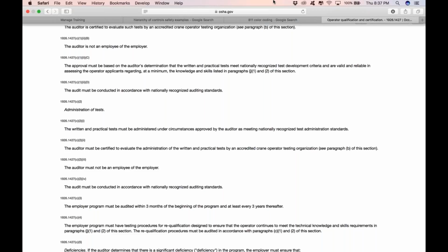And then public liability as well. Are we doing any work where we're going to be blocking any sidewalks, driveways, streets? Any overhead hazards to pedestrians or the public? What kind of lighting, signing, barricades, traffic controls are we going to use?